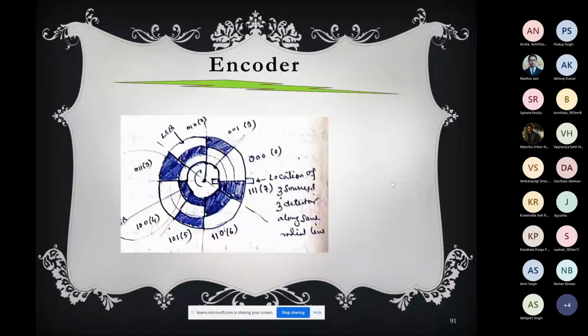The main takeaway is that whatever we have discussed till now, all the output is analog output, and we cannot directly feed it into the computer. But the computer is inevitable these days in measuring and in the control loop. It has to be. So if we cannot feed it directly, what do we need? We need an A to D converter, which will convert analog to digital, and then the digital voltage will be fed to the computer. The output of the A to D converter will go to the computer.